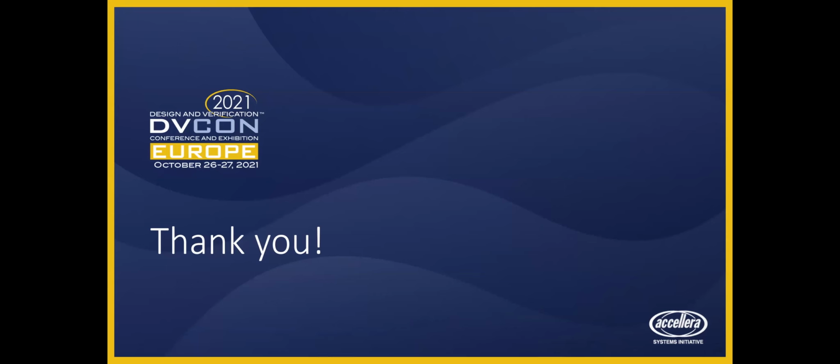Indeed, nice work, John. And just mentioning that when we talk about the resulting holes in the RTL, predominantly, we've achieved our statement and branch coverage as John showed. We have focused expression and condition items that remain, and we haven't gone into details here, but essentially that could be using our formal analysis tool to provide witness waveforms on how to address those remaining coverage holes.